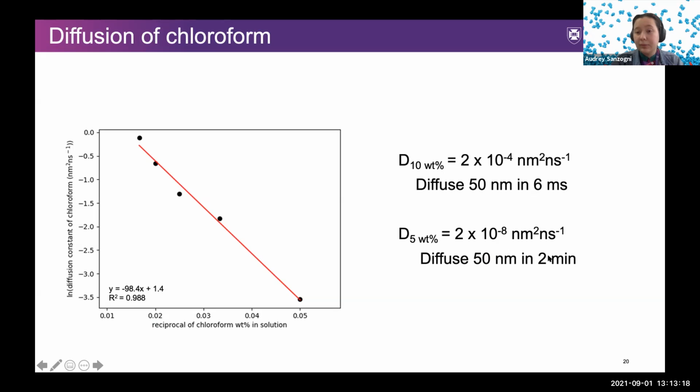And this is quite a thin film. These films can exceed 100 nanometers. So at 1 or 2 weight percent, this might take hours to days to leave the system, and in fact, some chloroform might remain trapped in the film, affecting the function of the device.